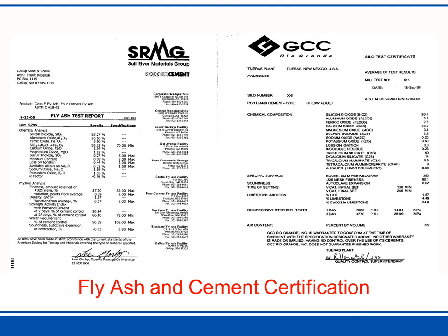The next thing I would include in the mix design was a fly ash test report from the supplier of the fly ash, and the cement certification. These were always provided to be hopefully within every 6 months. They can be very easily emailed to ready-mix producers on a weekly or monthly basis, whatever one would want.